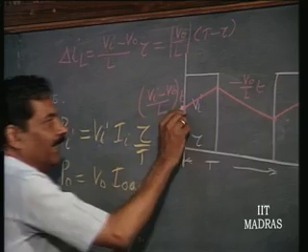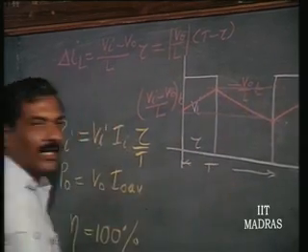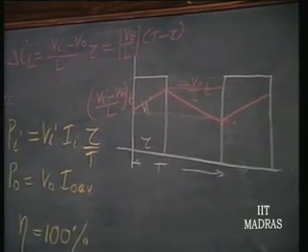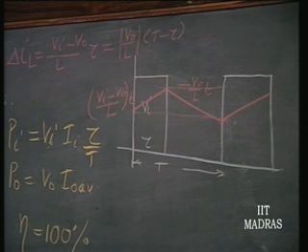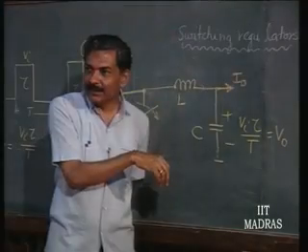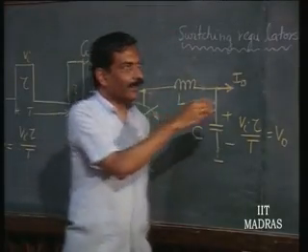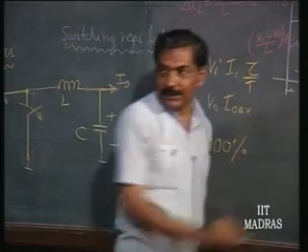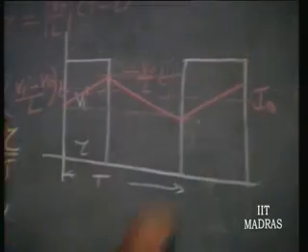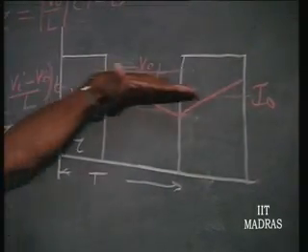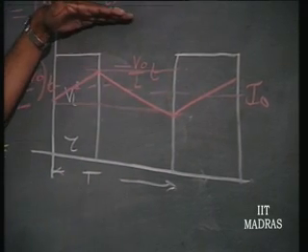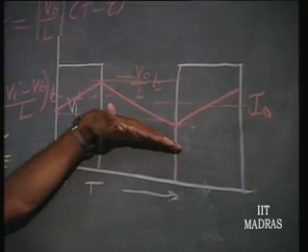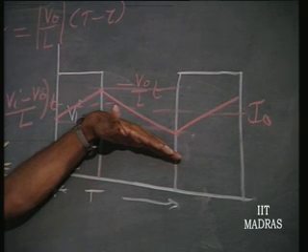Now, that is important because I must design the inductor also. The other current is negative only. Let us see, please understand this. Current is I naught. Where is this I naught flowing? Through this. This DC current cannot flow through the capacitor. So there is an average current in this which is I naught. Around the average current, the current is increasing above it by a certain amount and decreasing. So that is the idea of negative current. It is not negative.